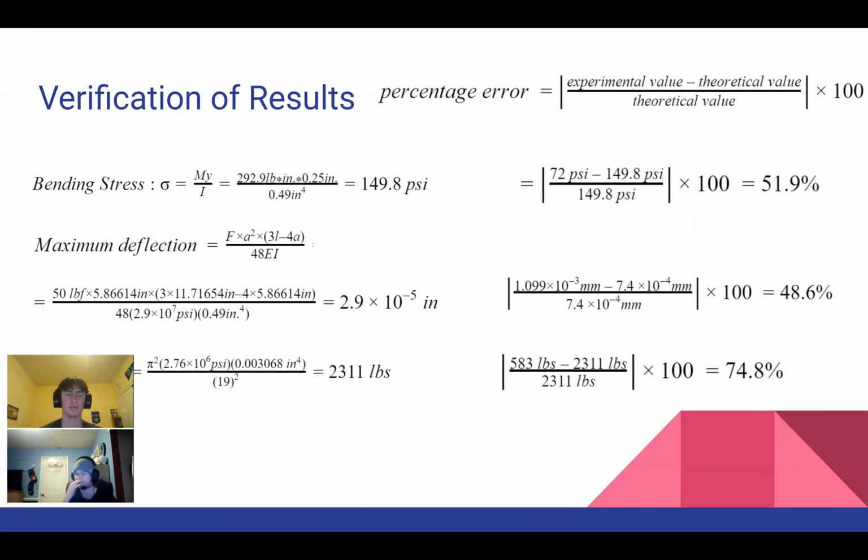To cap off this presentation, we compared the experimental results that we found in SolidWorks simulation to the results from our calculations using strength of materials, and the results can be seen here. There's a notable error, but this can be largely attributed to the fact that we had to simplify the boundary conditions when performing our calculations to make the calculations feasible.